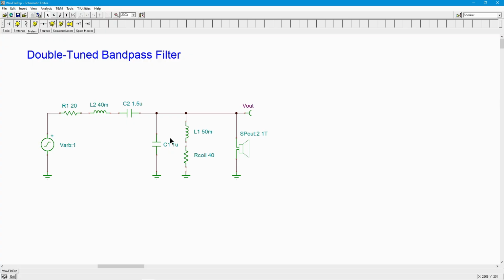You can, like I said, go back and forth, compare them, listen to it. Is it what you want? Great. If not, go back, alter it again, and you just cycle through this process, right? Of changing the circuit, running the sim, listening to the output. How does it work? And you just keep doing this until you get what you want. I mean, it's a very fast process if you think about it compared to breadboarding something. Okay?